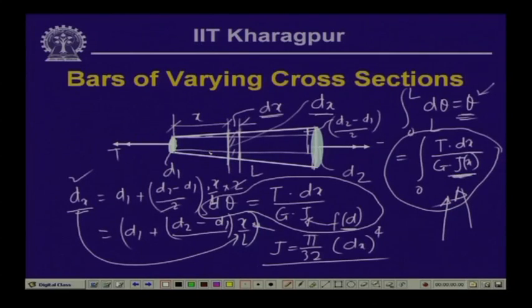Now, if we have varying twisting moment, instead of having constant twisting moment in the bar, then over the segments, as we have done in the past, where the twisting moment is non-uniform, between two such twisting moments we take the free body and find out how much is the twisting moment. In that particular segment, we again compute the stress, and we calculate the maximum of the stresses in these zones corresponding to the twisting moment. The maximum of these maxima will give us the maximum possible shear stress in the whole bar.